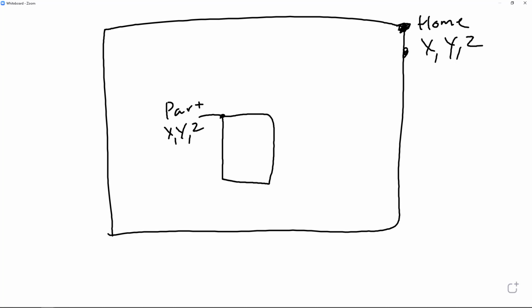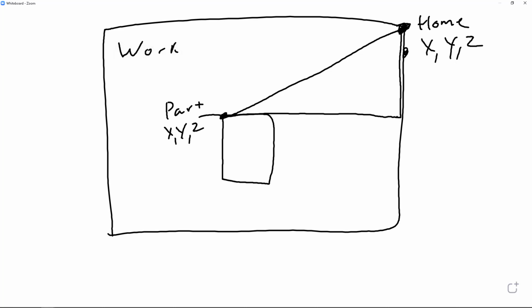But in X and Y, we need some sort of distance from home, which is standard, to this position where our program 0 is, which is an X and Y work offset. Okay?